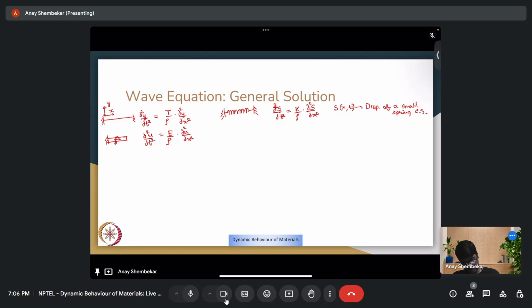We have also looked at longitudinal wave in an unbounded medium. Longitudinal wave has the expression ∂²Δ/∂t² is (lambda plus 2 mu) by rho ∂²Δ/∂x², where delta stands for dilatation and is given by Δ equals epsilon ii.